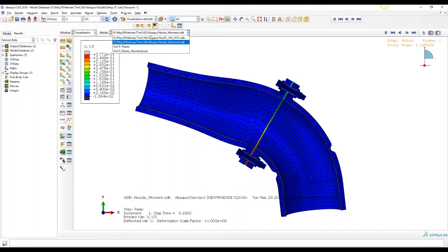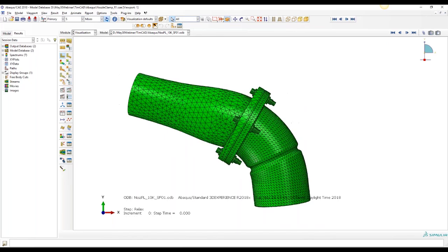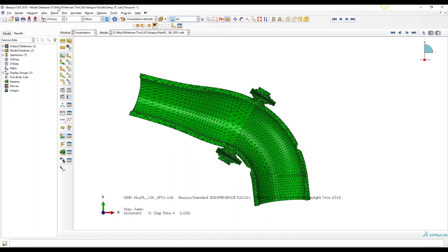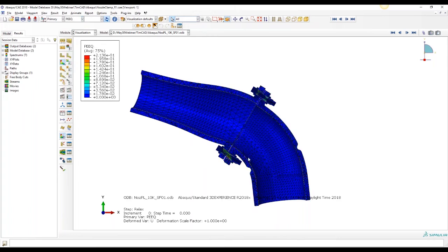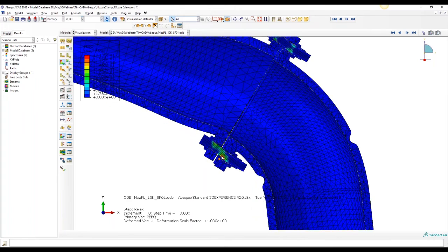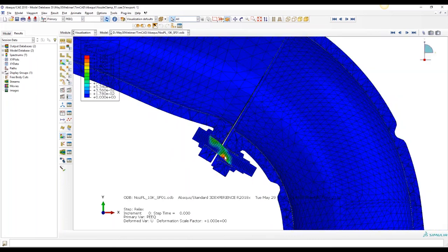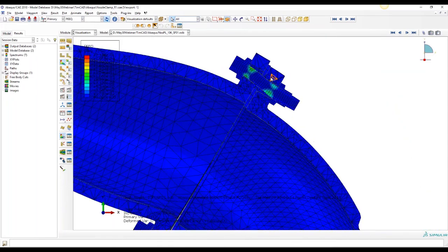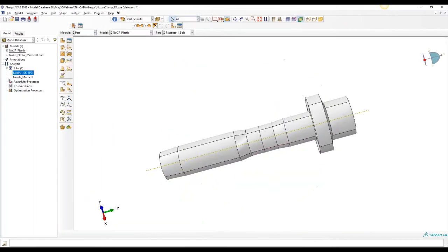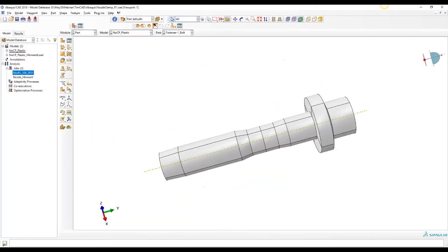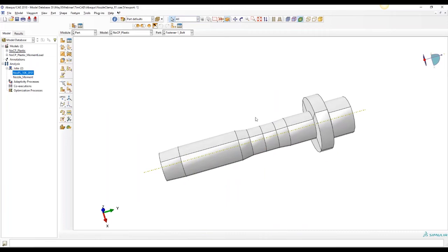We can do things like track plasticity. Probably what you'd expect looking at this shear loaded nozzle is if we cut a section through it, that we have some pretty significant plastic strains on the bolts. You may have noticed that those bolts were sort of necked down. I chose one, I believe, from an automotive application where it's got a significantly thinner spot, potentially a bolt that's torqued to yield.